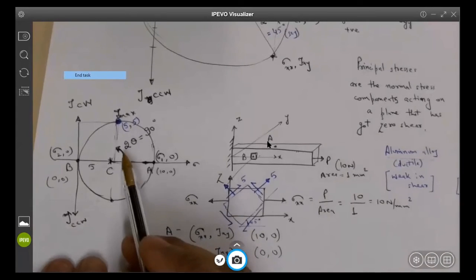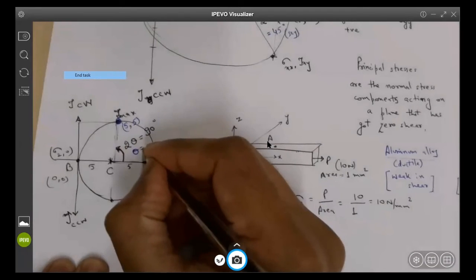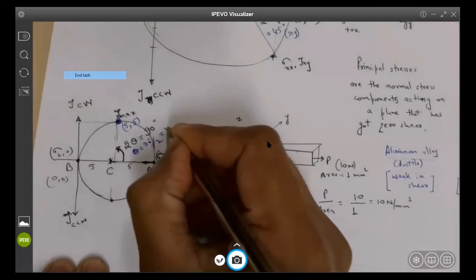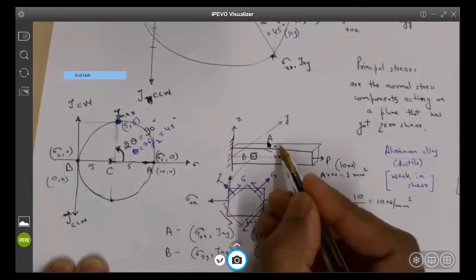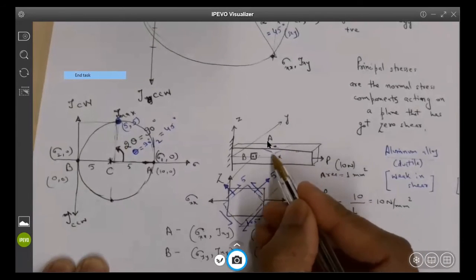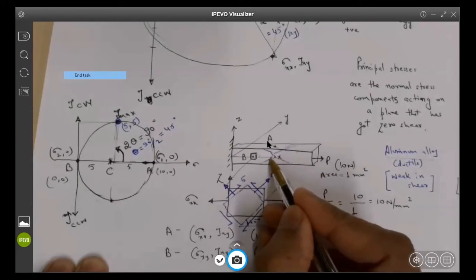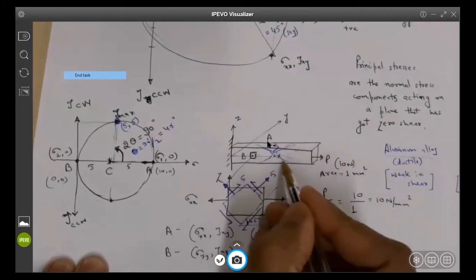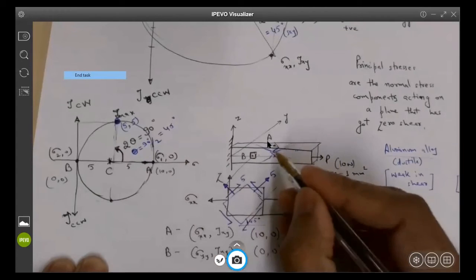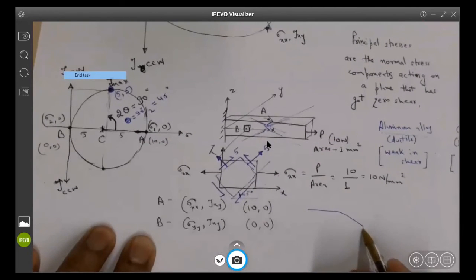Yes, you actually see there that the maximum shear stress is coming at the 45-degree plane, because it is half of theta, 90 divided by 2, which is 45 degrees. So if you rotate the plane by 45 degrees, ductile materials will actually start necking at 45 degrees. If you have seen a uniaxial test, you will see that the material fails by getting cleaved along a plane at 45 degrees. It basically breaks in 45-degree planes. So if you have seen it, it will actually fail like this.